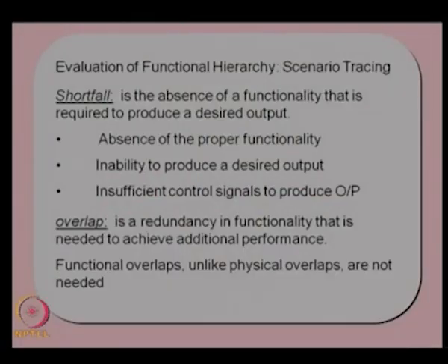We will be getting many diagrams like the A0 diagram, A1 diagram, A2 diagram, or level 0, level 1, level 2 diagrams, and all these diagrams can be combined together to find all the functions. Based on this we can create a functional hierarchy of the system, or the functions can be used to get the functional structure of the system. Basically we are decomposing the main function into the sub functions of the system.